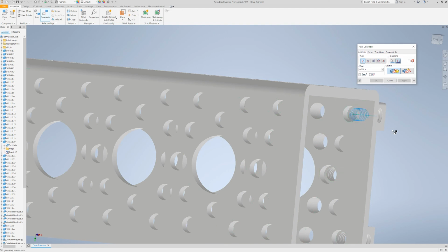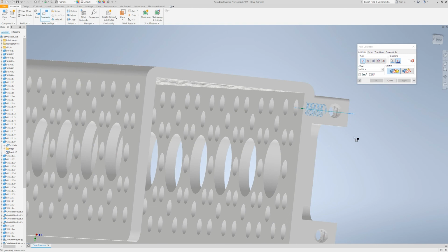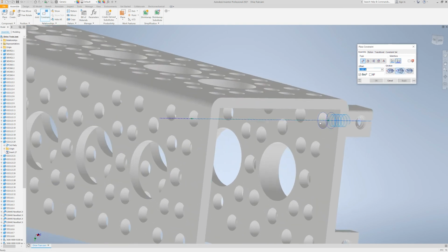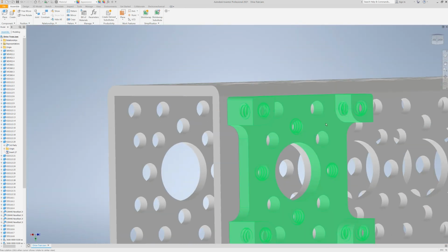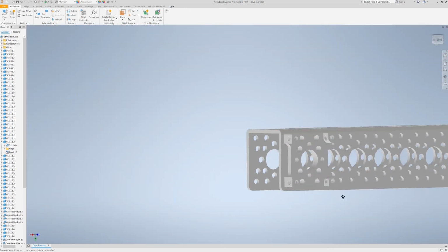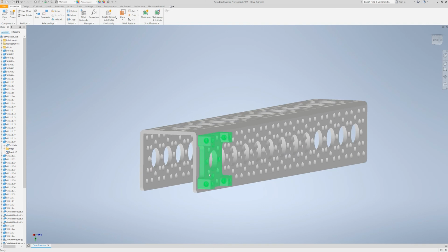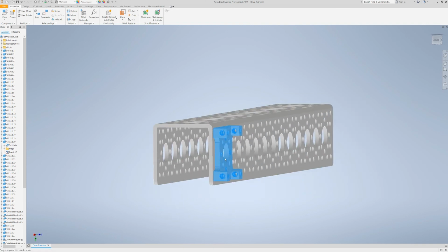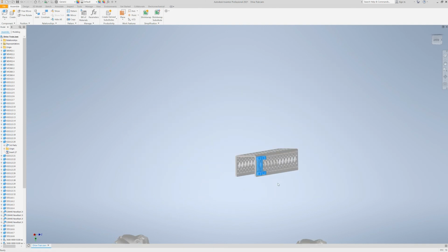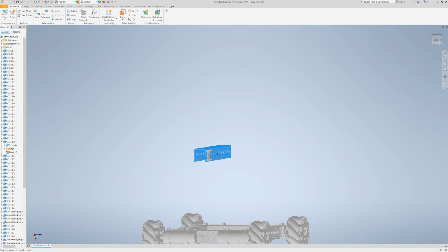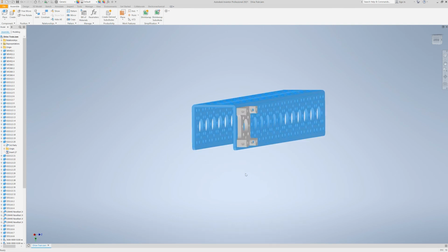You would click on the threading inside the quad hub mount, and the hole right here, apply, and there you go. You have successfully constrained this, basically adjusted its behavior to attach to this. So wherever this C channel goes, this quad hub mount will go. And essentially that's what constraints are used for.